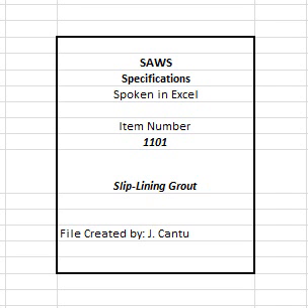This will not be permitted if the crown or any portion of the host pipe is severely deteriorated to the point where water may escape through the host pipe. B. Pressurize the annular space to the maximum permissible grouting pressure per manufacturer's recommendation with approval of the engineer. C. The contractor shall submit a detailed plan to the engineer that shows how the liner pipe will be held on the invert for a period of time long enough to allow the grout to set when buoyant uplift is